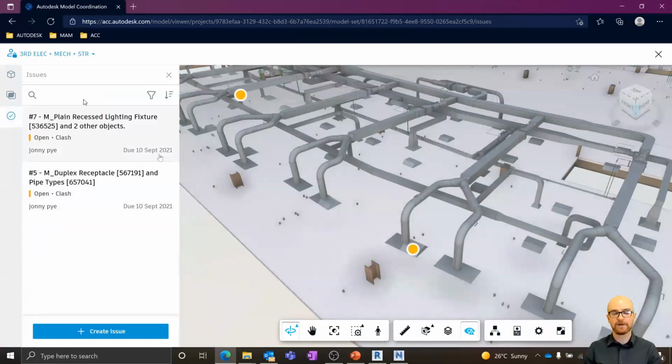And so the process for fixing this will be, now that this has gone to the designer to fix, they'll come back with their in review, like we did with the door, and upload the model. Once it's shared, it's going to automatically update the model in my model coordination space. And then at that point, as the person who may be coordinating the project, I can check whether that has actually been fixed or not. I'm not going to be able to upload the fix to this today because it does take a little while for the model coordination space to update. So it'll just be variable how long that takes. But I can go through the process for picking that up.